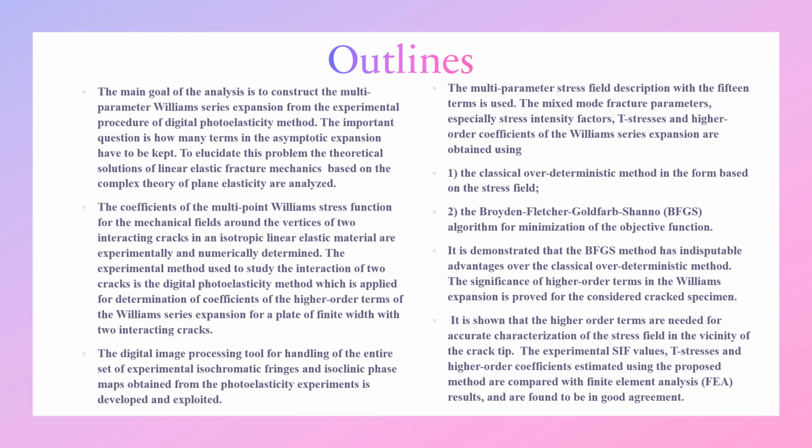It is demonstrated that the Broyden-Fletcher-Goldfarb-Shanno algorithm has undisputable advantages over the classical over-deterministic method. The significance of higher order terms in the Williams expansion is demonstrated for the considered cracked specimen, and it is shown that the higher order terms are needed for accurate characterization of the stress field in the vicinity of the crack tip.